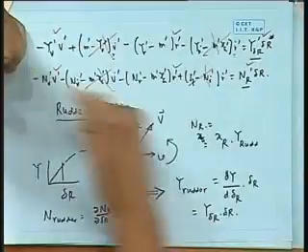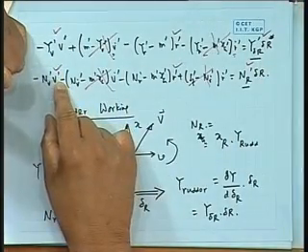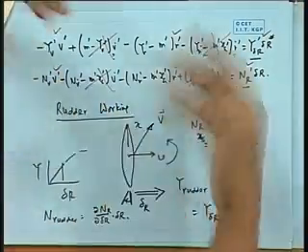Therefore, we will find out later on that if I give a delta R to be negative, the ship is going to turn on the other side. It is actually devised in such a way that if you turn it this side, the ship turns on the other side. That analysis we will do afterwards for a steady turn. If you want to show the transient, you have to solve this full equation, which cannot be solved so easily, okay. You can solve in the time domain, like step by step simulate, give a force, and see how the trajectory is. So, this is about the rudder part.